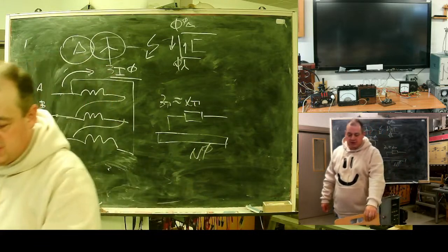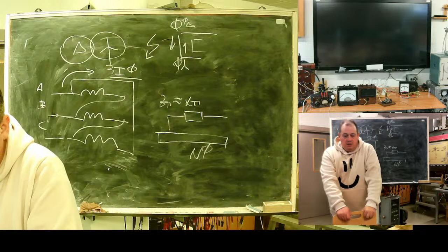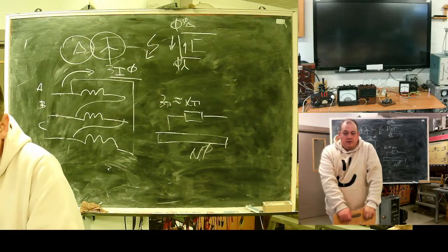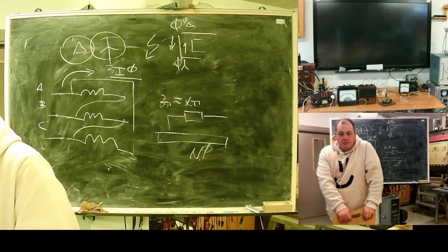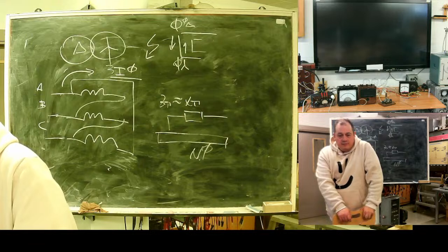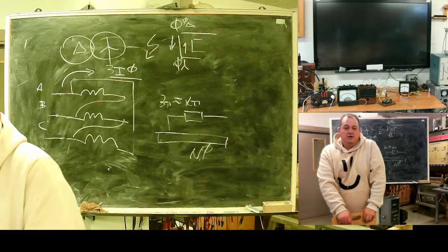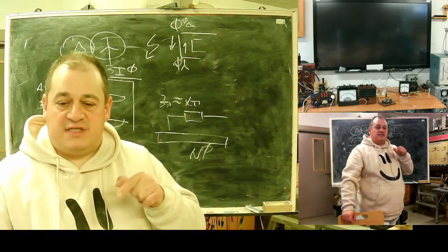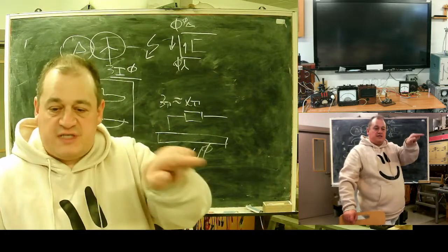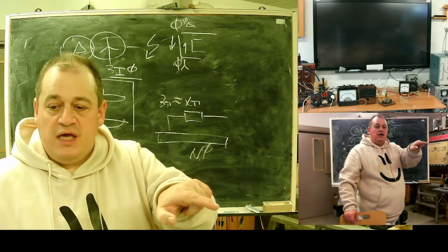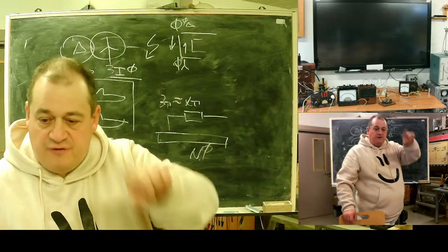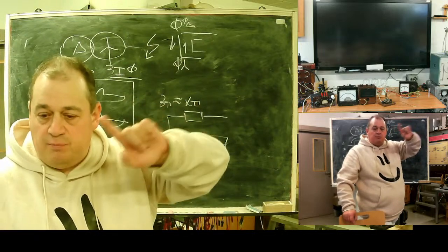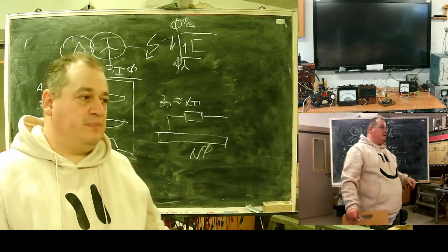It's important. When we speak of earth fault protection, we should understand that zero sequence current will flow to the grounded neutral if there is a delta on the other side.